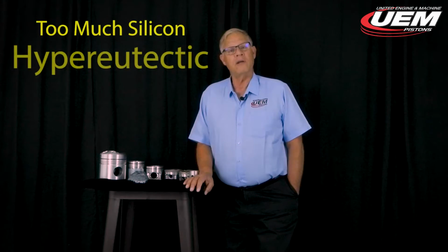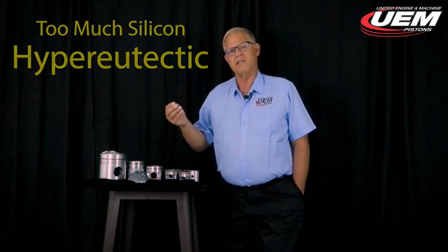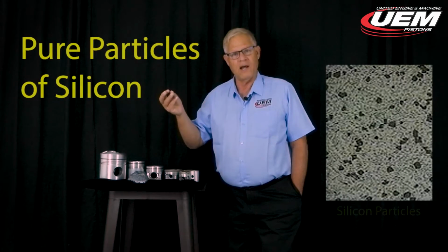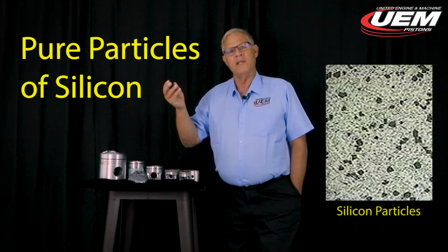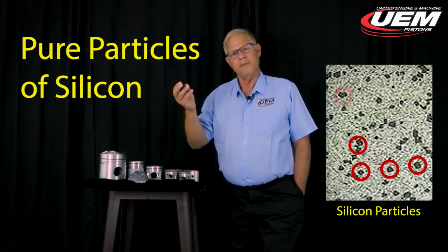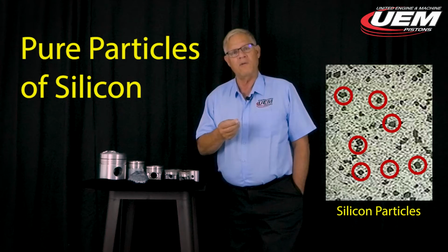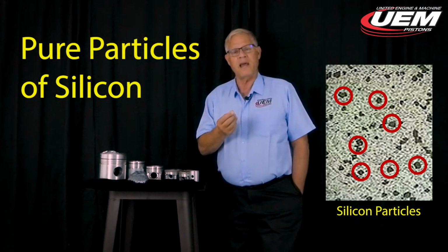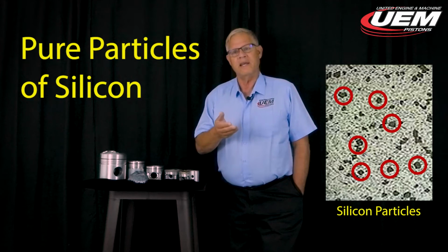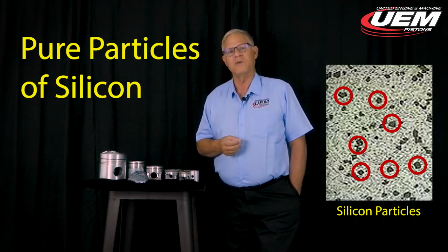In the case of too much, we call this a hypereutectic alloy. It's above the eutectic point. The way the alloy corrects itself is it starts forming pure particles of silicon throughout the whole casting. As it's doing this, the silicon in the remaining liquid starts lowering, and it keeps forming these particles until the silicon in the liquid gets to 12%. When it gets to 12%, at that point, it solidifies, and again it solidifies like a pure element.